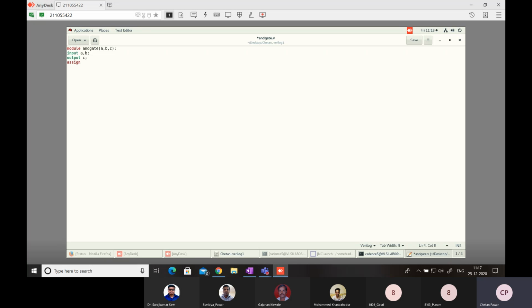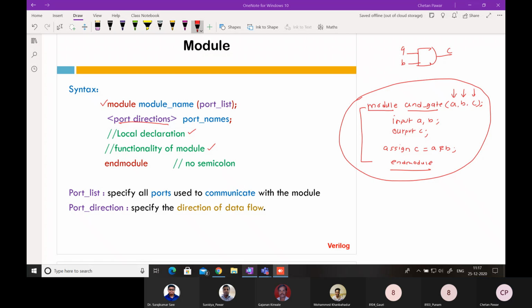So the Verilog language supports sequential statements and concurrent statements. So sequential statement means what? One after another execution will happen, right? So if I write like this, that A is assigned to B, then B is assigned to A, then A is assigned to C. So first this statement will get executed. After that, this statement will get executed. Okay. So this flow is called a sequential flow.